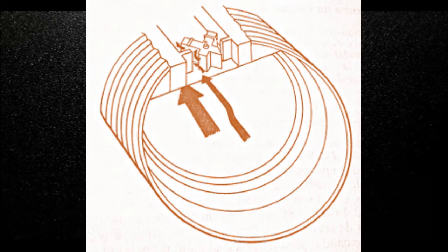The oscillating flow method has a small orifice located in its body that generates a differential pressure and causes the fluid to pass to the measured area. This contains an oscillating valve that disturbs the flow of the fluid. As this turbulent flow passes through the opening, a zone of low pressure is created behind the valve, causing the valve to oscillate at a frequency directly proportional to the flow rate.